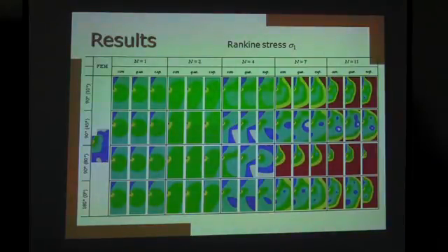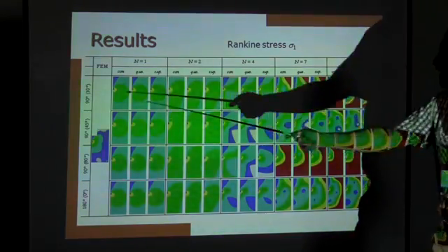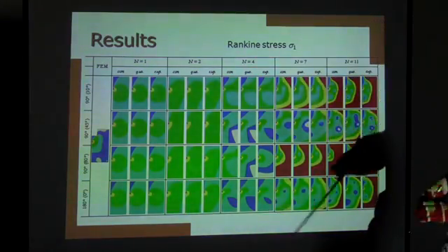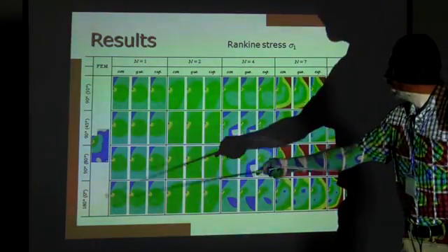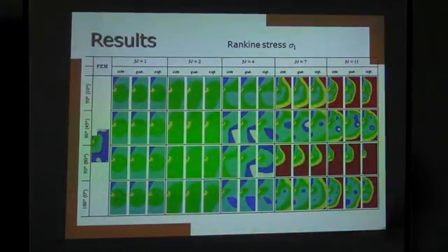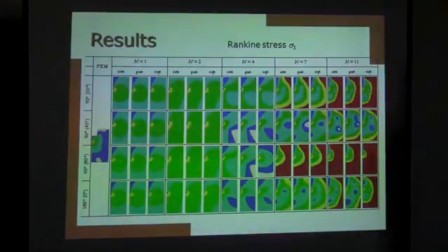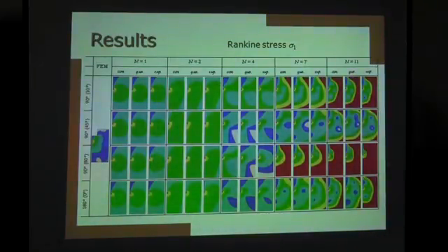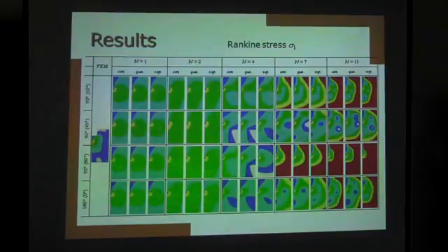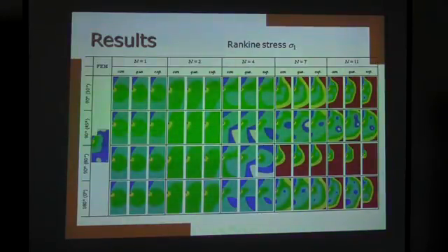Those selections are described here using angular sections of 90 degrees, turning about 10 degrees, then 90, 45, 90, 80, and the whole half space, with constant, quadratic, or exponential distribution of those nodes from the crack tip. You can see that the results can depend quite strongly on the selection of nodes which we used for the fit of the truncated Williams series.